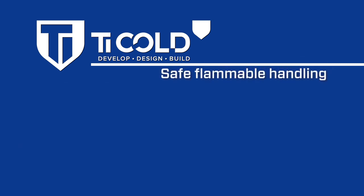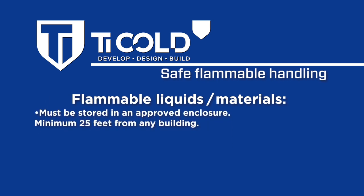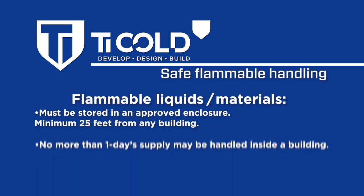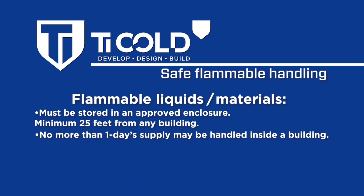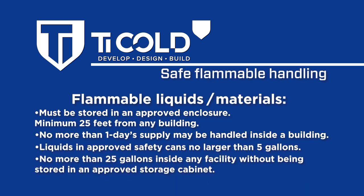Safe flammable handling. Flammable liquids and materials must be stored in an approved enclosure, minimum of 25 feet from any building. No more than 1 day's supply may be handled inside a building. Liquids in approved safety cans no larger than 5 gallons. No more than 25 gallons inside any facility without being stored in an approved storage cabinet.